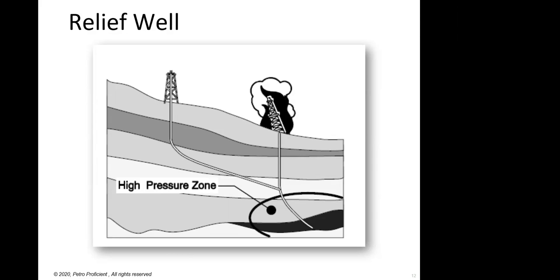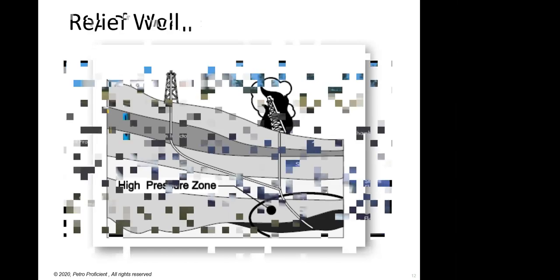An example of relief wells is Macondo, in the Gulf of Mexico, where we had a blowout in BP. So they had to drill a relief well, and eventually that blowing well was capped after several months, I think 1 or 2 months, using a relief well. And this is how it is basically killed. It takes a few months, sometimes more than a month, to kill.